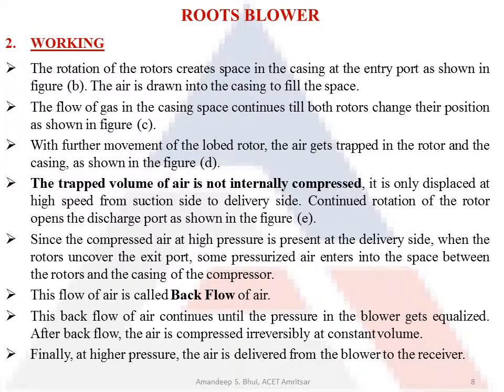Since the compressed air at high pressure is present at the delivery side, when the rotor uncovers the exit port, some pressurized air enters into the space between the rotors and the casing. This flow of air is known as the backflow of air. This backflow of air continues until the pressure in the blower gets equalized. After the backflow, the air is compressed irreversibly at constant volume.